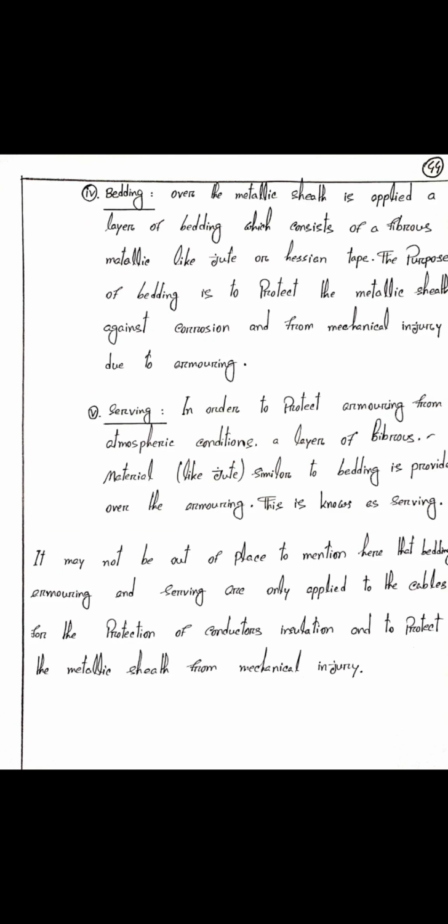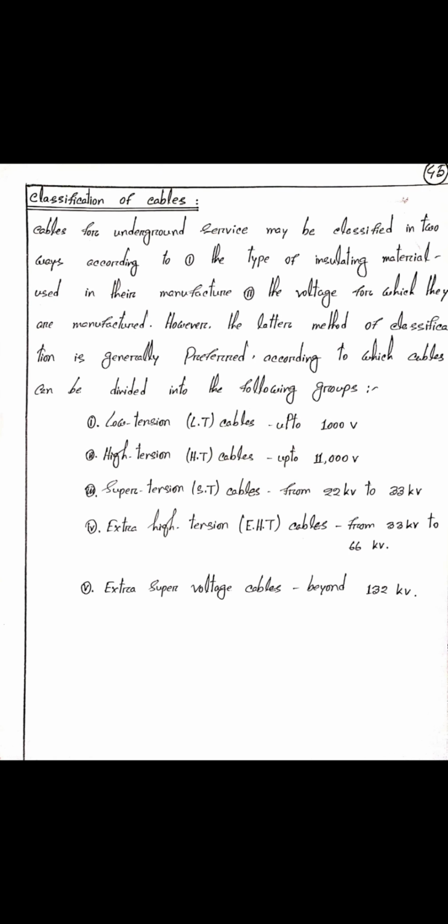Bedding, serving. It may not be out of place to mention here that the bedding and the serving are only applied to the cables for the protection of conductor, insulator, and to protect the metallic sheath from mechanical injury. Classification of cables.